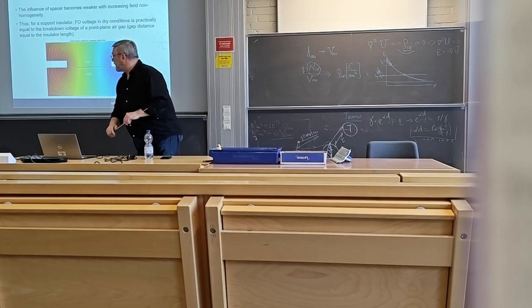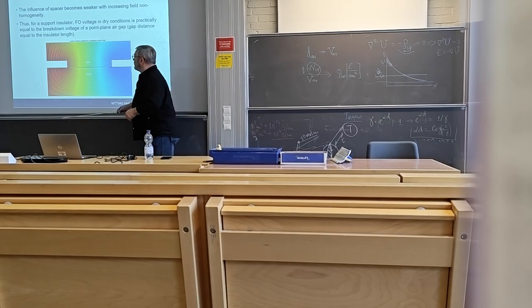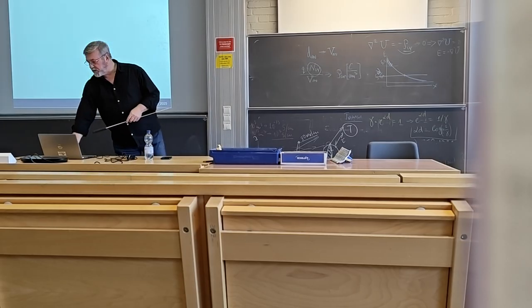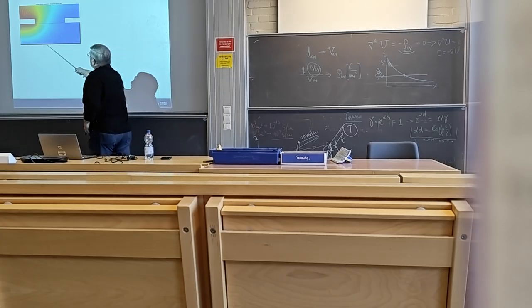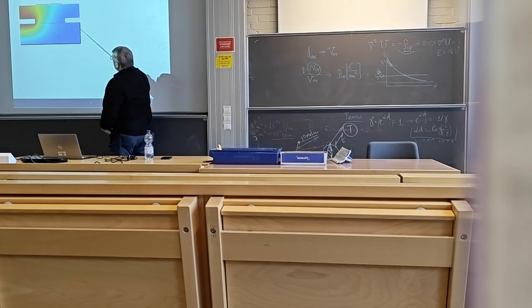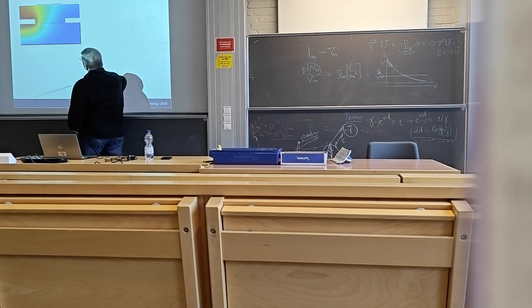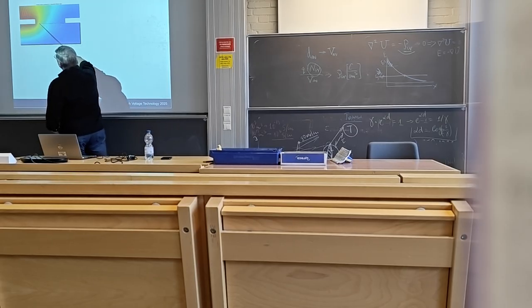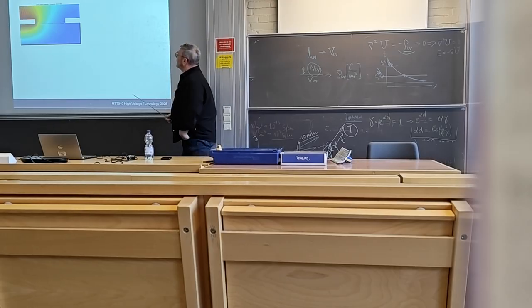This is just the axial field here. So that means that we don't have any normal components acting here. But if you create the conditions for the normal components, just assigning ground here, you see the things completely change, because then you have lines going like that, and then you have really strong, or high density of, potential lines and strong field on the interface.